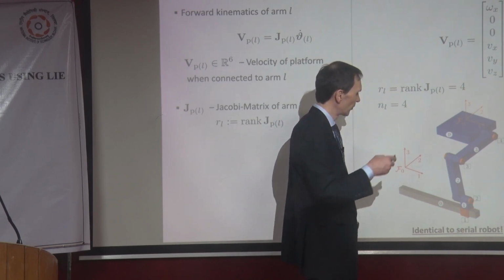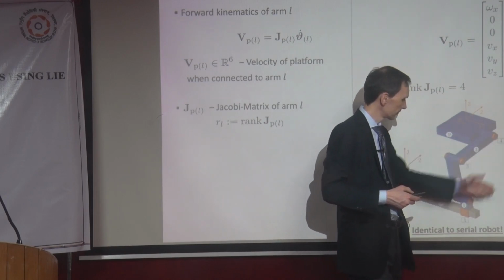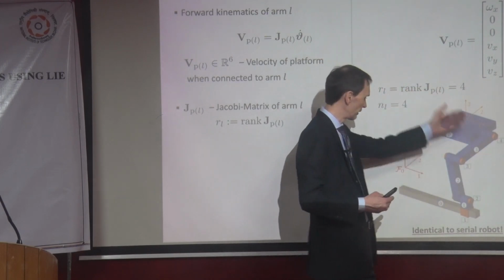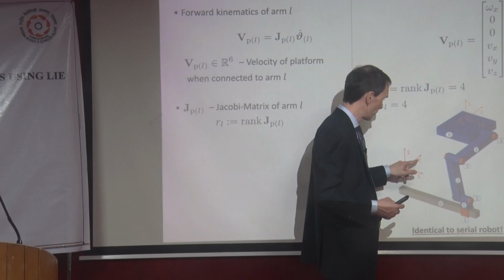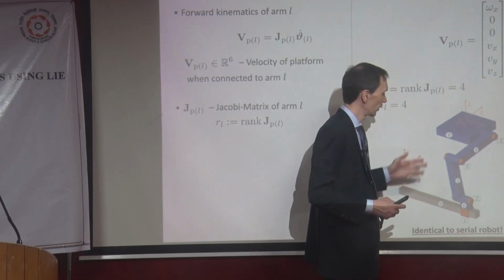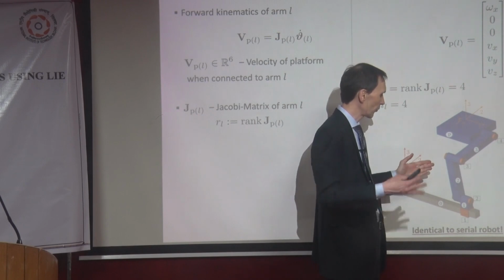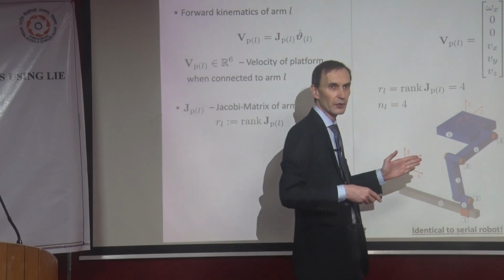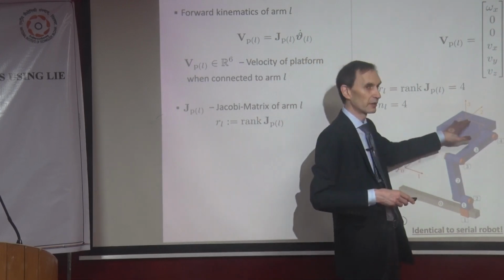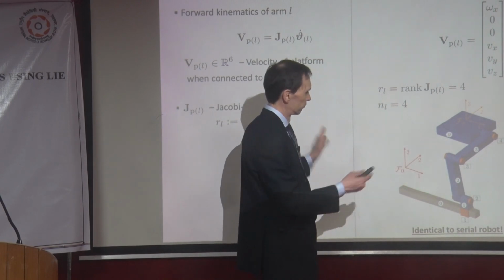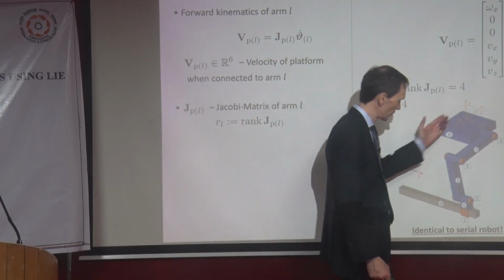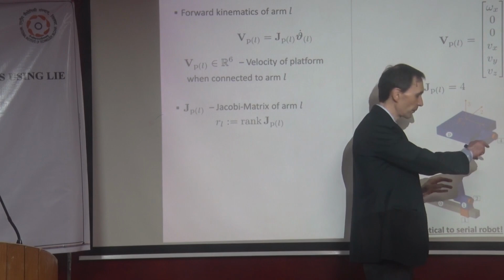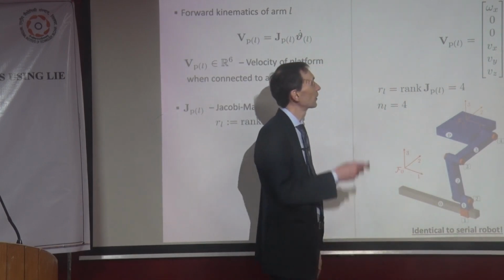Then you do a planar motion apparently, because this revolute joint 3R mechanism does some motion in that plane, in the YZ plane. So you certainly get translations in x, y, and z independently. That's why we have the x, y, and z linear velocity in the twist of the platform. And then it should be obvious that due to the revolute joints, you get this planar motion, which also includes rotation about the x-axis, and that's why we get this omega x.